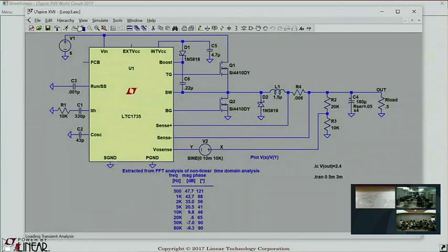Okay. So we've gone all the way around the feedback loop. We've found two poles. Each pole can get you up to infinitesimally close to 90 degrees phase shift. Two poles can get you up to infinitesimally close to 180 degrees phase shift, up to infinitesimally close to phase reversal, up to infinitesimally close to oscillating.